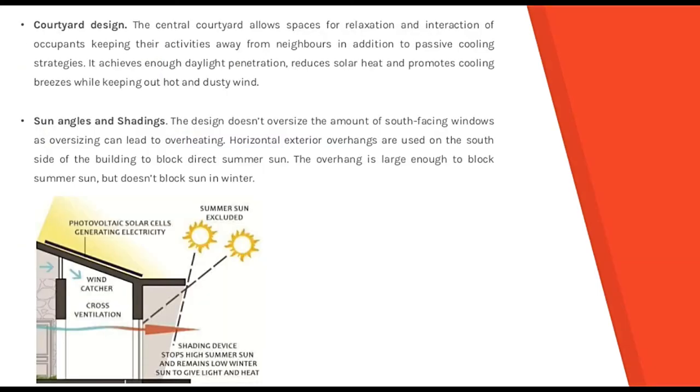Alright, so let's go ahead. The courtyard design. The central courtyard allows spaces for relaxation and interaction of occupants, keeping their activities away from neighbors. In addition to passive cooling strategies, it achieves enough daylight penetration, reduces solar heat, promotes cooling breezes while keeping out hot and dusty wind. So ganito yung magandang design. It's called a courtyard design.